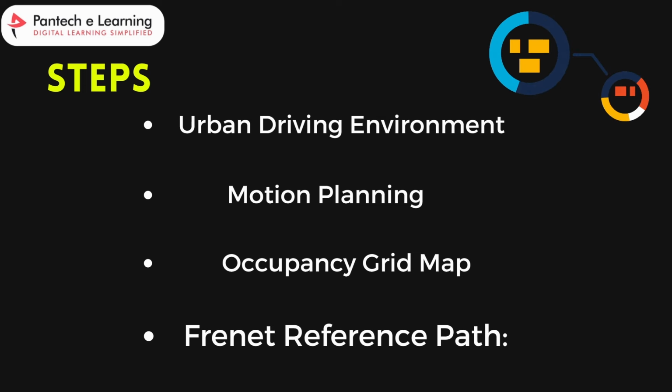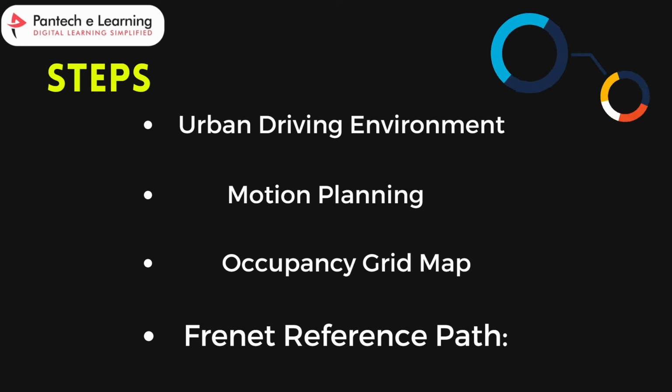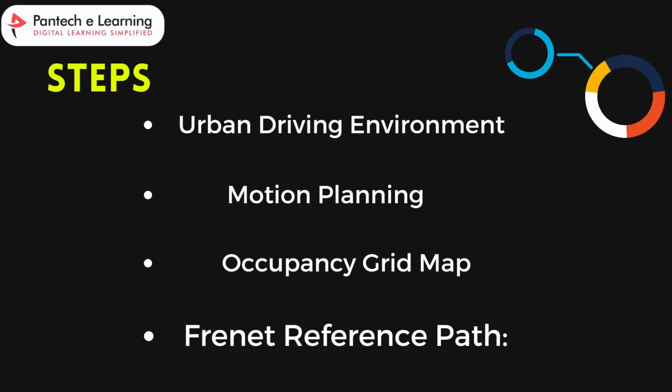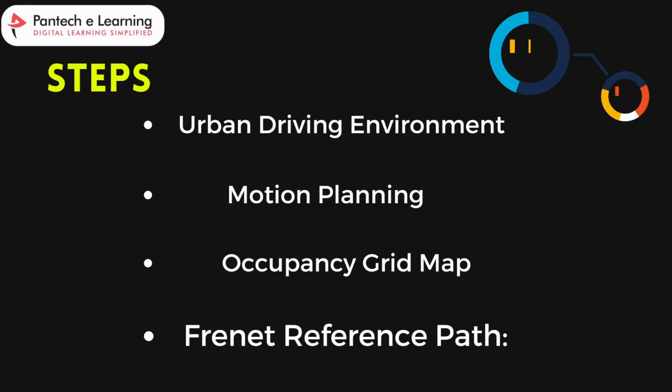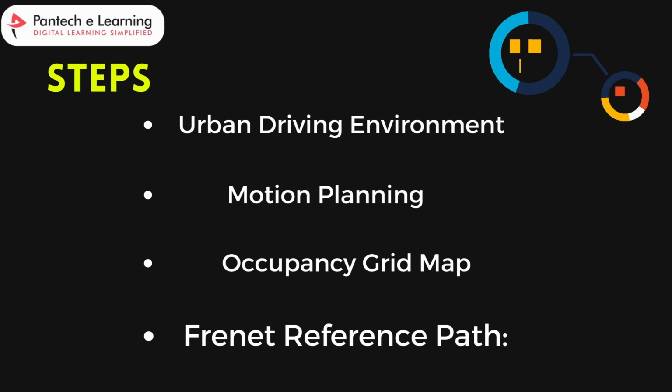Mainly we are going to discuss this example. We explore dynamic replanning for the autonomous vehicle using a local motion planner. This local motion planner is responsible for generating an optimal trajectory based on the global path, that means information about the surroundings. This information about the surroundings can be described in two ways: one is a discrete set of objects, the other is a discretized grid.